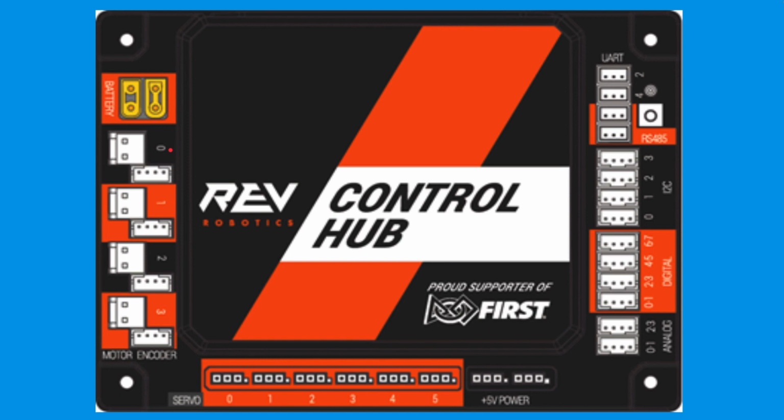It is the same process for servos. You want to plug in your servos into these ports right here, and note these numbers right here as they will be used for configuring your servo. Next, you will need to configure your motors and servos inside of the driver station app. We will provide a link in the description with a video on how you can do this.